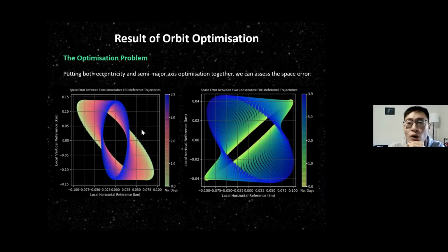For the near equatorial orbit, we can see that the reference trajectory without drag oscillates around plus minus 150 degrees and has this nice spinning shape. I told you, nature always has a way of making beautiful patterns for us to sit back and appreciate. And we've done the same for a polar orbit too. Notice that the polar orbit's standard deviation is around 40 meters, which is really, really good.